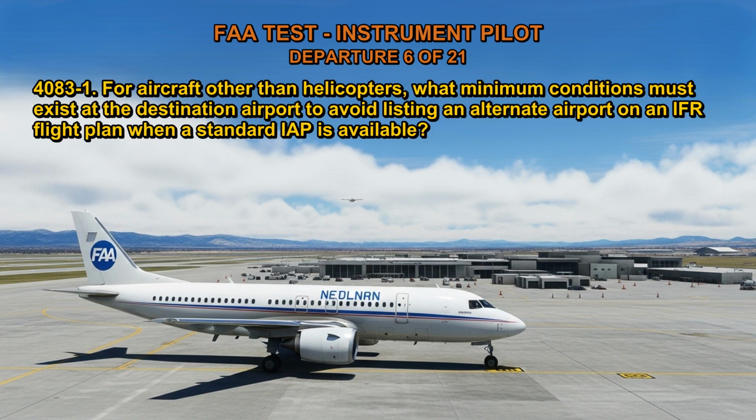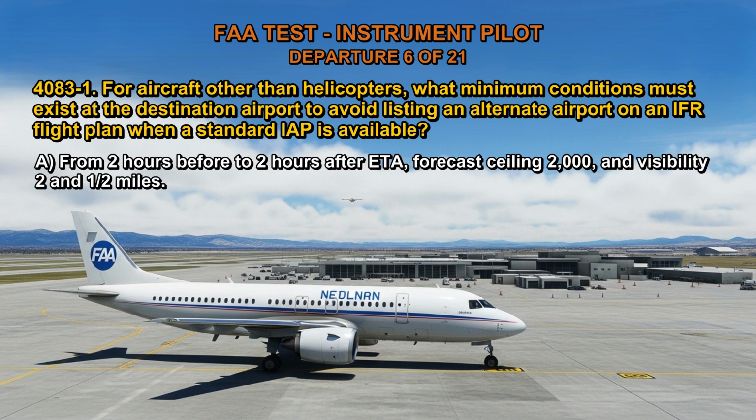4083-1. For aircraft other than helicopters, what minimum conditions must exist at the destination airport to avoid listing an alternate airport on an IFR flight plan when a standard IAP is available? A. From 2 hours before to 2 hours after ETA, forecast ceiling 2,000, and visibility 2 and 1/2 miles.